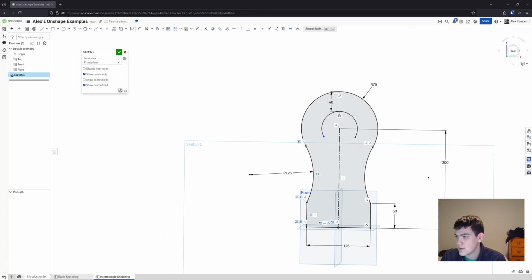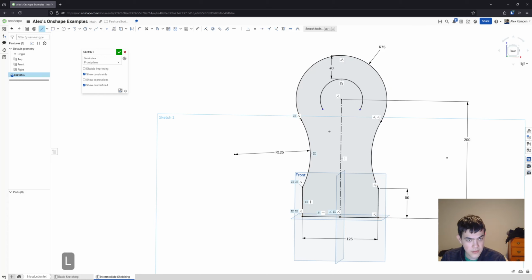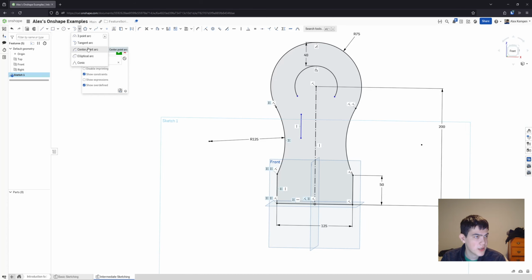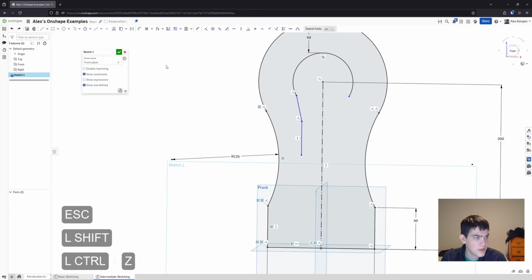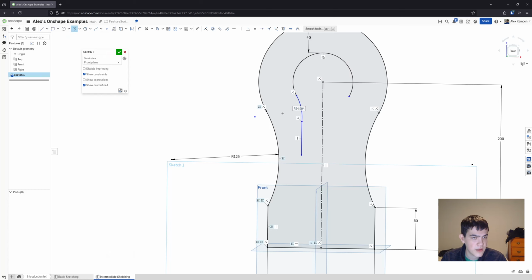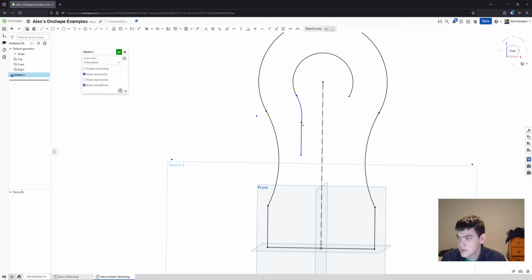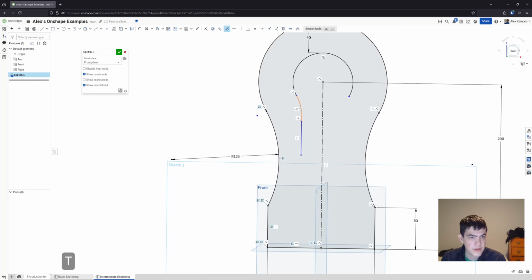Yeah. And then we're supposed to add a line, which is vertical. Okay, and then we're supposed to connect these with an arc. So here, okay, they recommend using tangent arc, that's fine. So I'll grab a tangent arc and I'll click here. Oh, that was just a line, oops. Yeah, so I'll grab that. And then I'm gonna wanna add the tangent on the other side over here. So it's tangent over here and tangent over here, so I have a nice smooth connection.